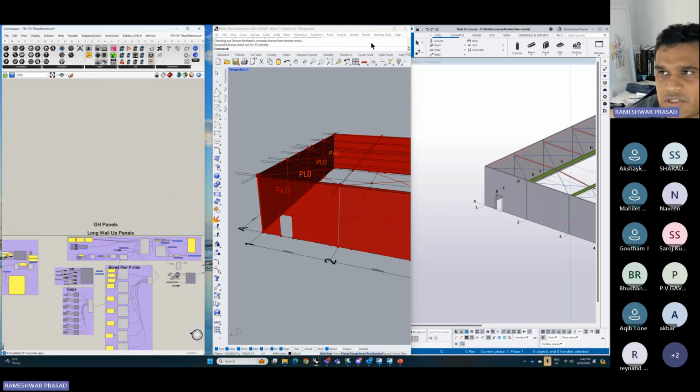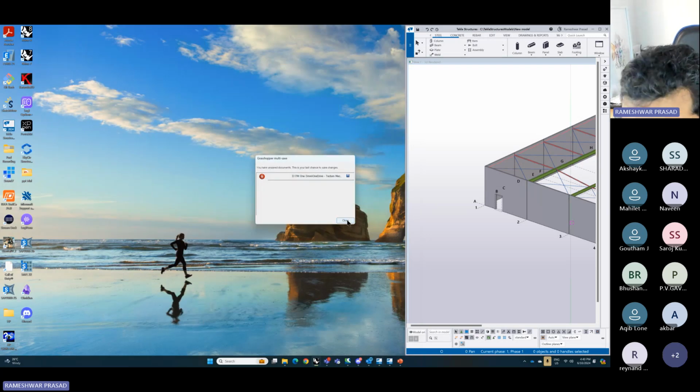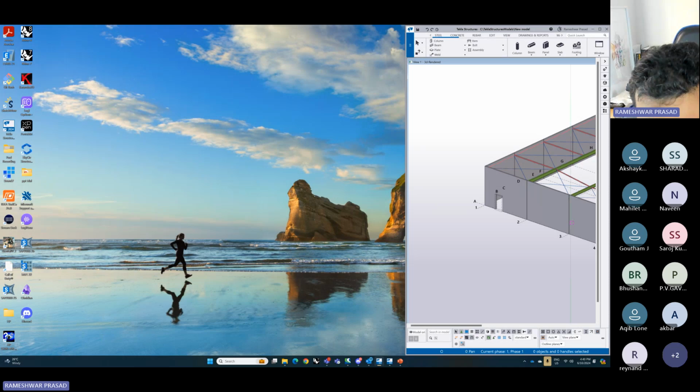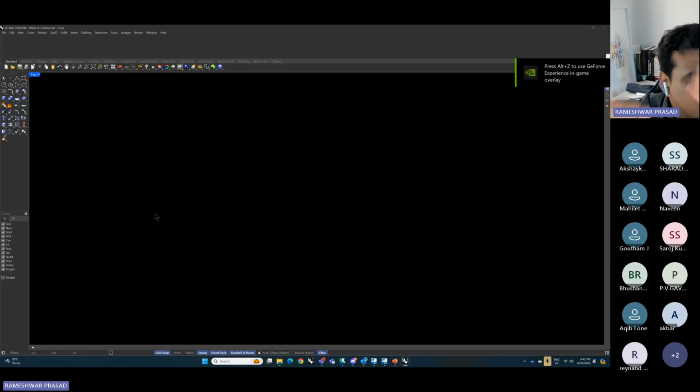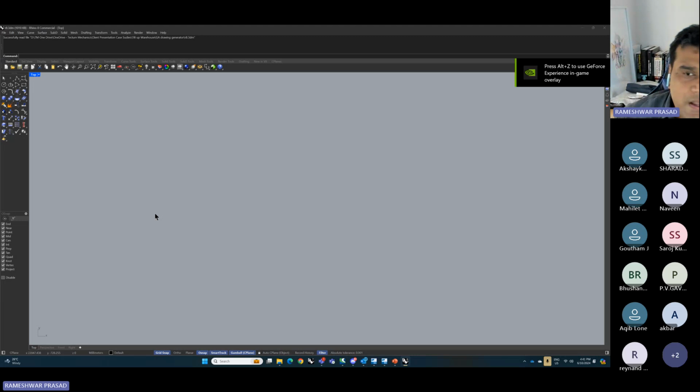What I'd also like to demonstrate is something called a panel lifting analysis. So once these panels are cast on slab, okay, before that, I'll show you how we are working on generating drawings. So once these panels are modeled, you need to generate the GA drawing of the panel, which shows the CG of the panel, the lifting point CG. So you have 4 or 6 lifting points, whatever it is, and you need to find out the center of gravity of those lifting points, and then you have the CG of the panel as well. And I think there's a rule which states that the CG of the lifting point should be above the CG of the panel so that it doesn't rotate downward, but it rotates upwards, something like that.